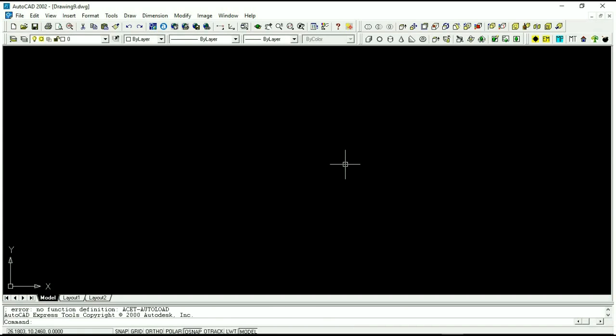So now what I'm going to do is I'll start a new drawing. And now I'm going to make the component. I'm going to make the stud wall itself. So when I open up my default AutoCAD drawing, I'm looking down on the building. So it's my plan view. So I want to bring the parts in so that their profile is in that view. So when I bring in the plates, I'm looking down on them. So I'm looking at them along their length and their width. So I'm already in the proper UCS view.